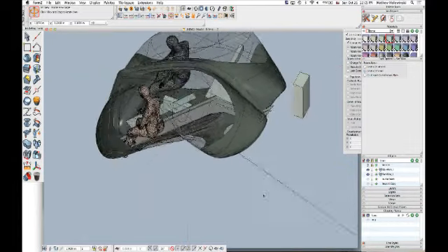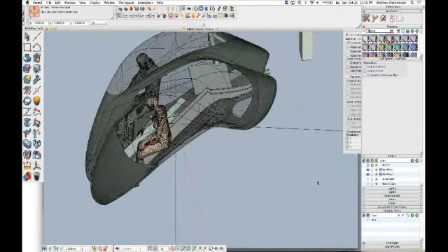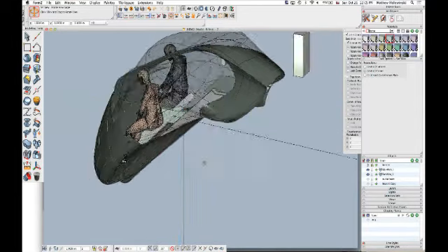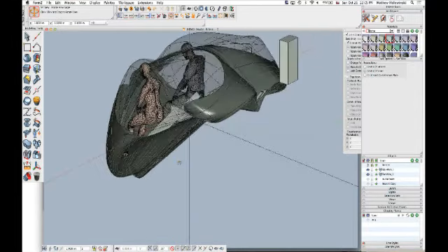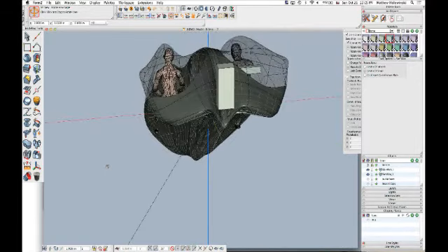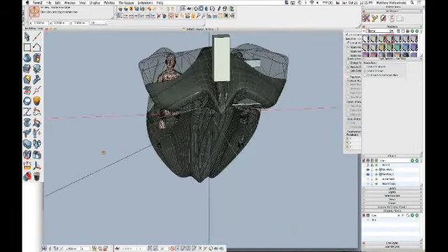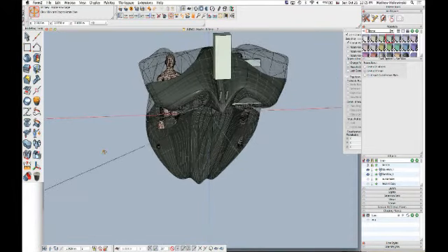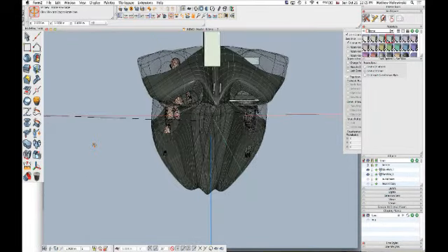I just built a rectangular box, transformed it into a wedge shape, and pulled a few pieces, and then went into the sub D and went back and forth to see the results between the box and the sub D surface. And then you can really just pick pieces. And what I find is always tricky is when you need to get to a mirror image of it. You can do it with an instance that gets updated and mirrored, but that's sometimes a bit buggy.